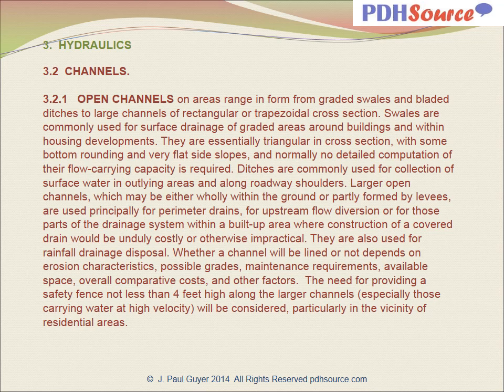Whether a channel will be lined or not depends on erosion characteristics, possible grades, maintenance requirements, available space, overall comparative costs, and other factors. The need for providing a safety fence not less than 4 feet high along the larger channels, especially those carrying water at high velocity, should be considered, particularly in the vicinity of residential areas.